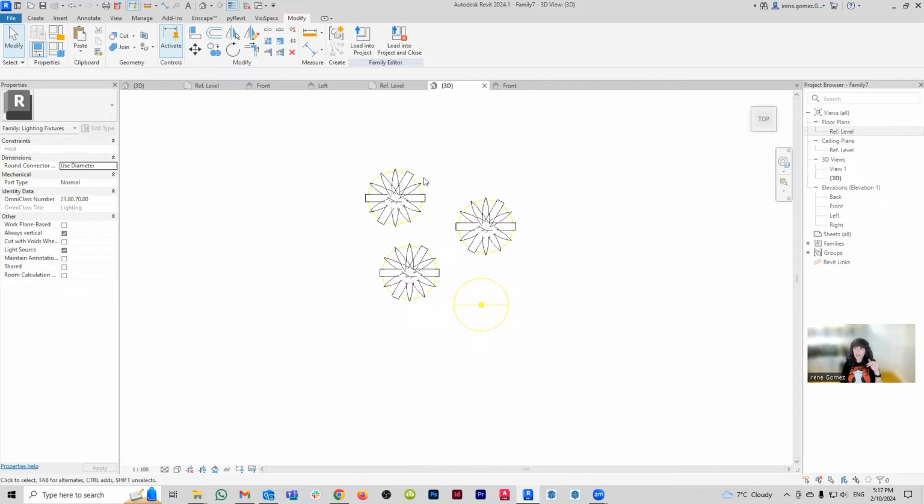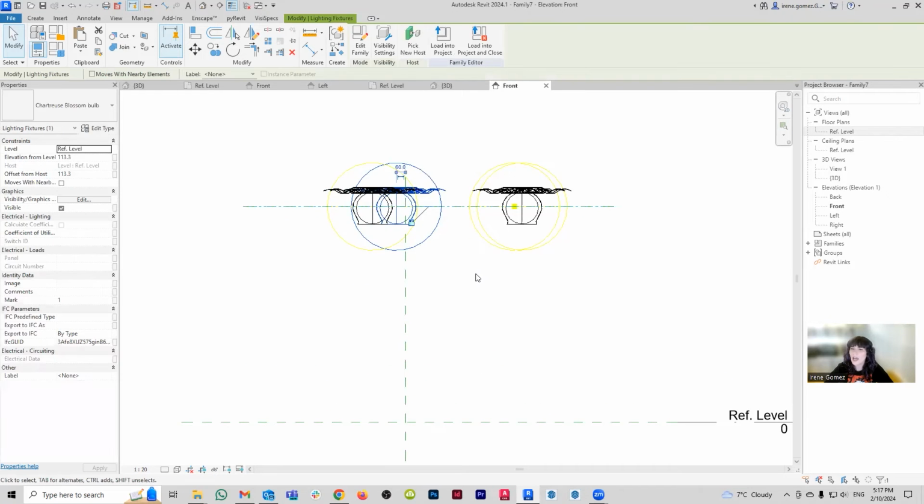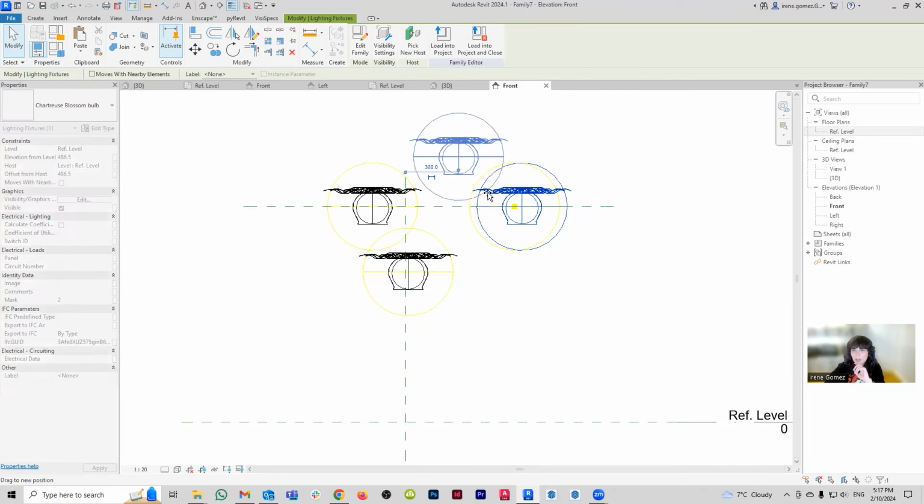And the reason that I do the cables only now is because when you think about the cables, all of them need to go to whatever your ceiling is. But then all of them have to go to whatever the height of these different lights is. So if you do the cable when you're doing the initial bulb, all of the cables would be the same length, and then some of them are basically going to go through your roof. Instead here, I can control them as two different elements. So I can come here and say, in that case, I don't want these guys to be perfectly aligned with that. So that's fine. I'm going to say you are going to be lower and then you are going to be higher.